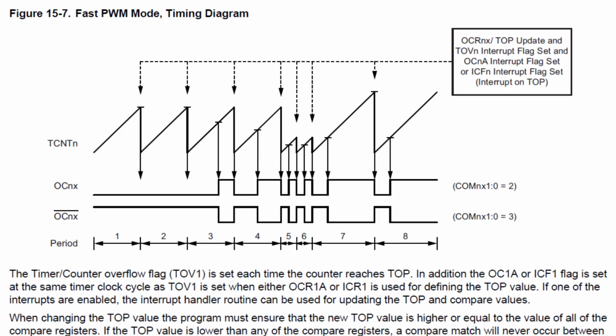Now look at the 3 timers of the Arduino. These can be configured with an additional threshold, so they can output a PWM signal on their own without the need of any time-consuming interrupt routine. With this they can go up to 8 MHz.